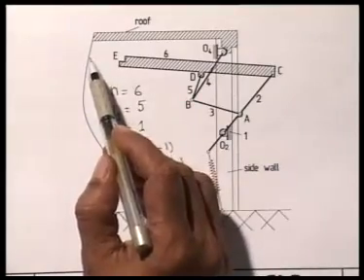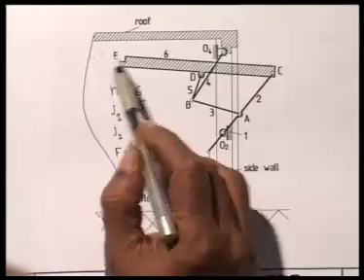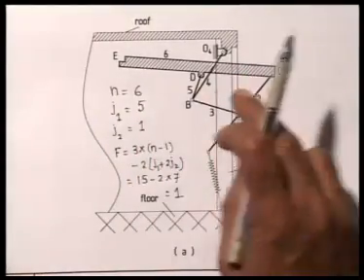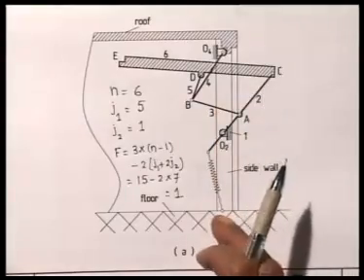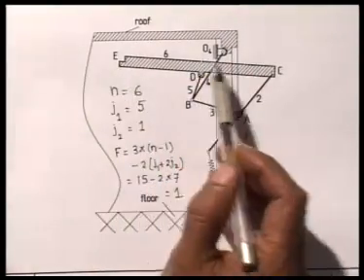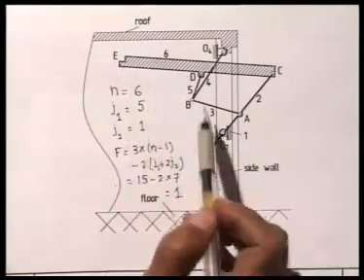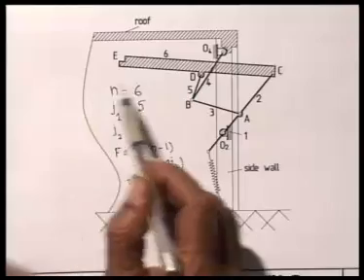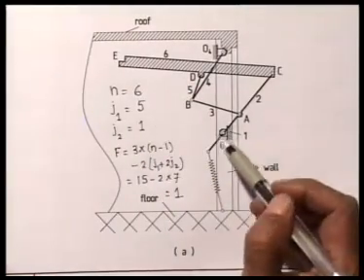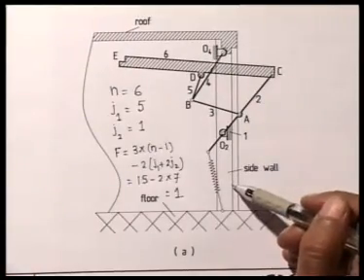That the door board, when the garage is open, should remain parallel to the roof, that is horizontal, and in the closed position, when this linkage is moved, the door board becomes vertical to close the garage. From this horizontal to vertical transition, the door board should not take too much space inside the garage because the car is kept here and that will interfere with the car. The rest of the mechanism is mounted on the side wall.